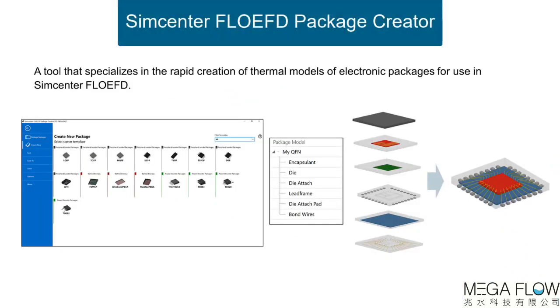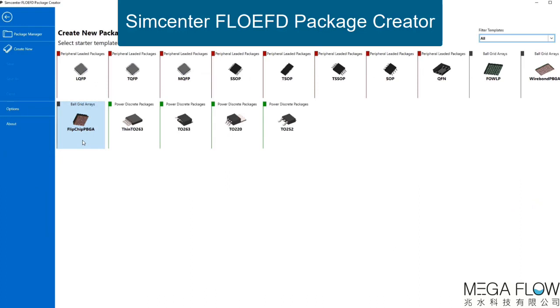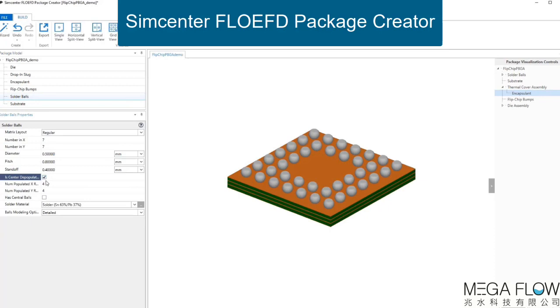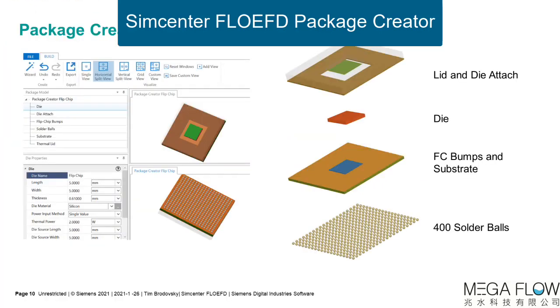FloEFD's Package Creator is a tool that allows you to quickly create a detailed thermal simulation ready package. Here we see the start templates for different types of packages and how easy it is to modify a package. In this specific workflow, we use a flip chip ball grid array with 400 solder balls and an aluminum thermal